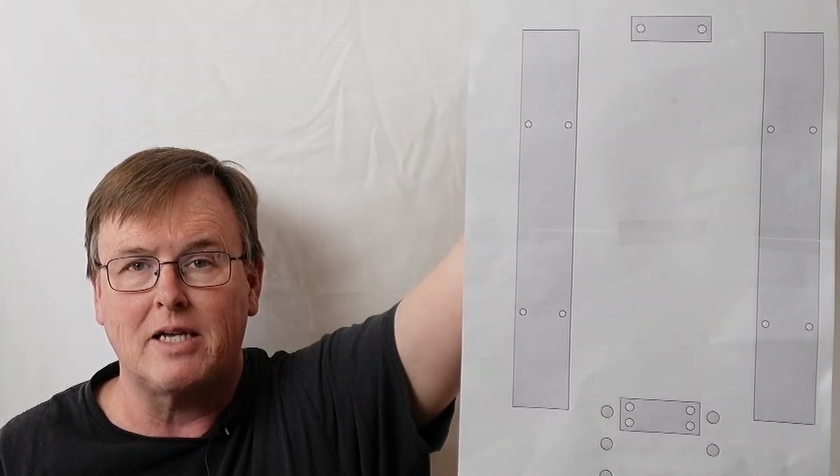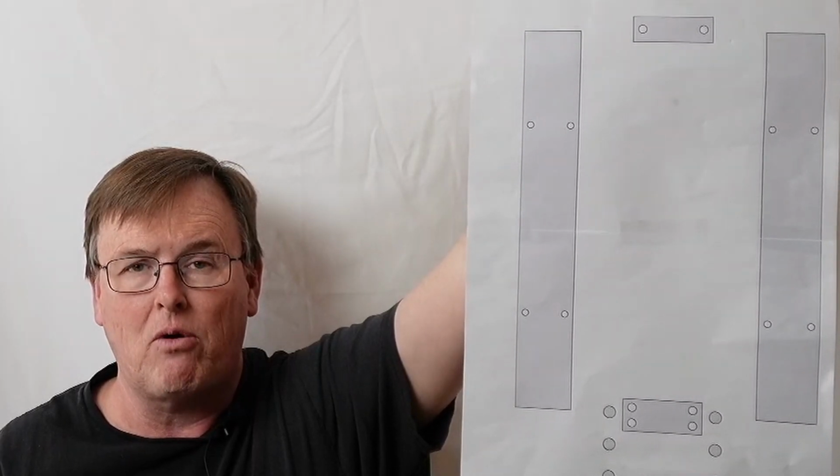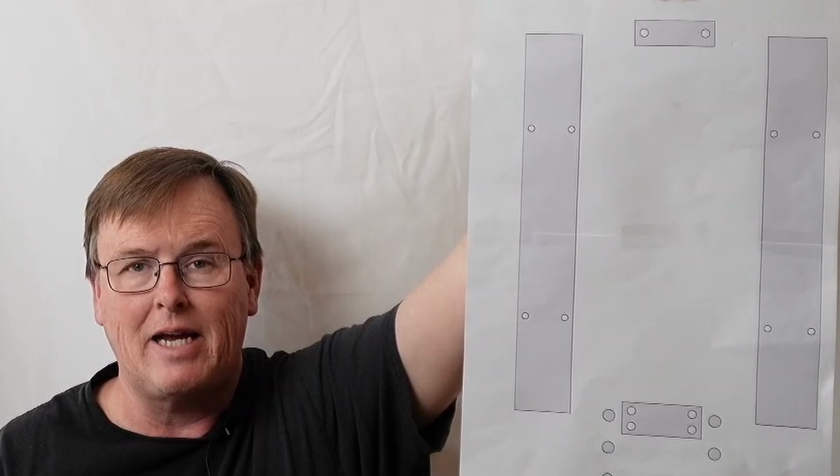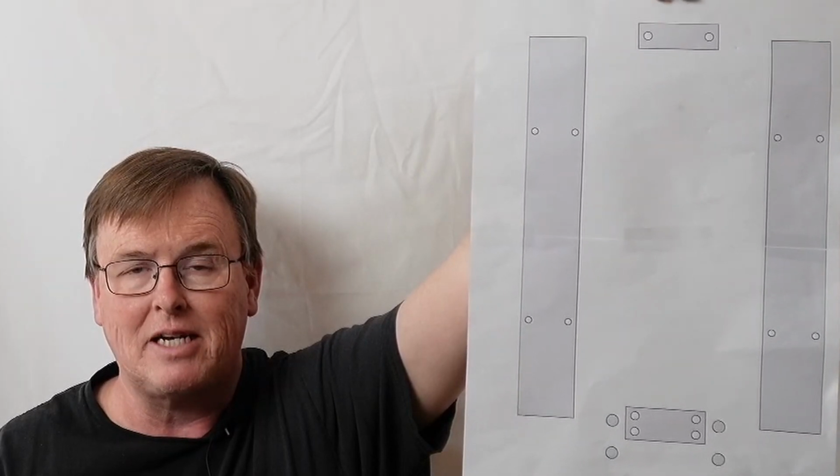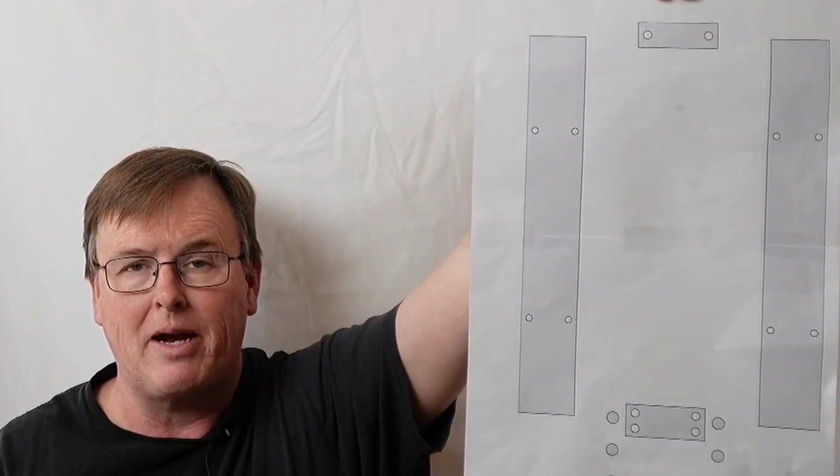You're going to do what you did in episode 7 and episode 10, meaning if you want to use it, you're going to go down and left click, select all the text, right click to copy to clipboard, go into OpenSCAD, which is free and downloadable. Once you've installed it, you're going to go to the editor window and paste in your clipboard, hit F6, and lo and behold, you're going to be able to generate this.